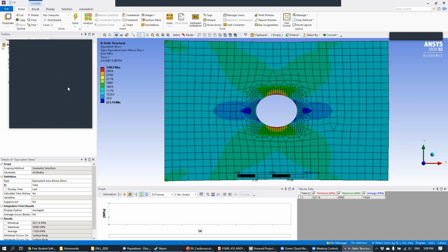How would Ansys deal with something if the pressure applied would actually break the bar? Because it's not real time, so would it just show a separation? Right. It won't actually separate. Because right now you're assuming a linear material model, so it'll show a stress that might be gigantic, that might be above the yield stress of this material. But that's the limitation of this. There's another type of analysis that you can run in Ansys called buckling that can show that.